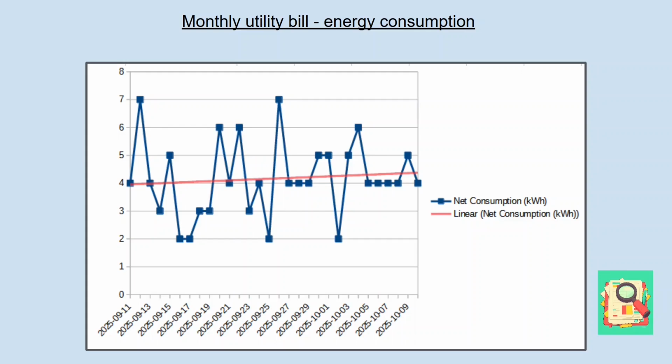That is to find the daily energy requirements, or energy requirements on a 24-hour basis, find out the peak sunlight hours, and divide the energy by those hours. So for example, if the energy requirement for the day is 40 kilowatt hours and the peak sunlight hours is 5, we find that the solar panels should be rated at 8 kilowatts.